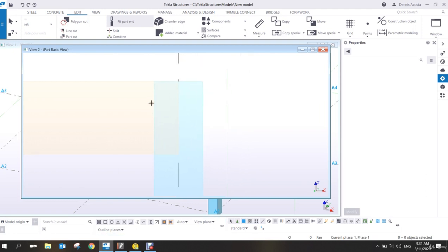All right, so again, pick the beam. Now this time, if I click this beam, look what will happen. Object not found. Why? Because it's transparent. This is what I was telling you yesterday. If it is transparent, you cannot just click on the surface of the beam, but you need to click on the edge. So click on the edge, and then 1, 2.